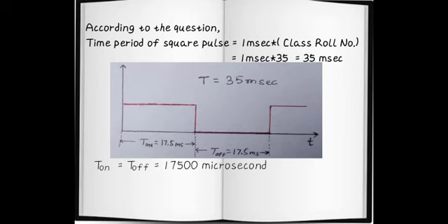Now we have to deal with four registers: TL0, TH0, TMOD and TCON if we are using timer 0. TL0 and TH0 are used to set the number of counts it has to count. As we know, the 8051 timer uses up counters.